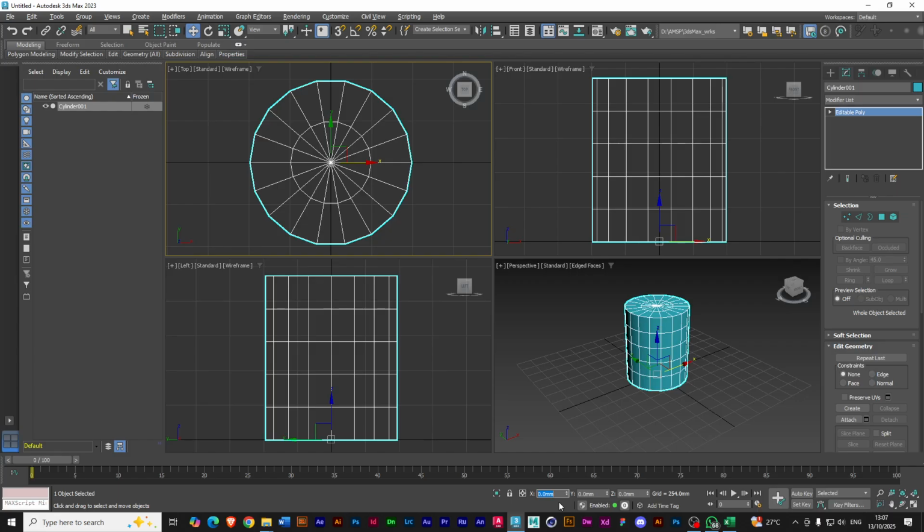Go to your select, go to your move tool. Okay, so zero the next. We want to bring out, I think it should be in the front view. That's this one on top here. I want to select this spot and this spot and extrude them out. Just this and this. So I need to switch either from here or from here to polygon mode. That's clicking on this arrow, you can switch polygon mode, or you just click it here.